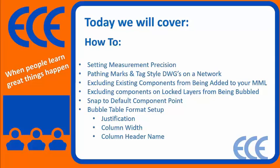Excluding existing components from being added to your MML. We know that projects go through different phases, phase 1, phase 2, and you may have to add new piping to your model. So we'll look at a way to exclude any existing piping and just make the master material list, the MML, from your new piping.